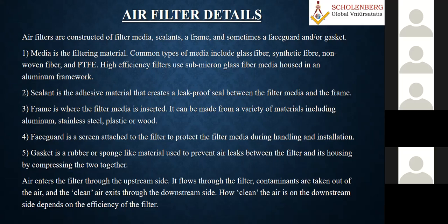They specify all the things. Then what type of sealant, what type of frame, is it an aluminum frame or a stainless steel frame, and even the gasket, because when we are going to install this, what quality of gasket. So as I told you, media is the filtering material. Common types of media include glass fiber, synthetic fiber, non-woven fiber, all these types of things.